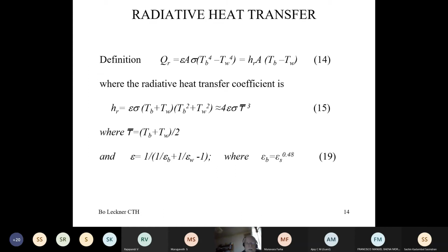Okay, so this is the radiative term. If you remember previous studies, radiation is dependent on the fourth power of temperature in Kelvin, the Stefan-Boltzmann coefficient, the surface, of course, and in this particular case of radiation, epsilon, I have not changed it, is emissivity. Otherwise, in fluidization it's usually voidage, but here it's emissivity.